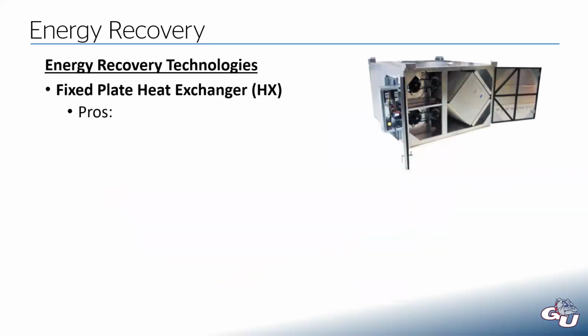The pros of this kind of system, they're also fairly effective. Not quite as effective as an energy wheel, but they're competitive with them. Most of the ones I've spec'd are between 70 and 75%, which is still quite a bit better than a pumped runaround system.